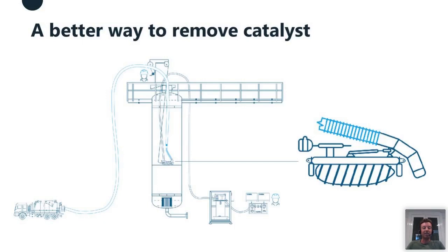The other elements that are shown in the drawing are the hydraulic power pack. It's all hydraulically driven, which was chosen to ensure that we could meet the ATEX Zone 1 rating requirements inside the vessel with the risk of explosion. It also has cameras, which again are ATEX rated, and then there's the operating module.